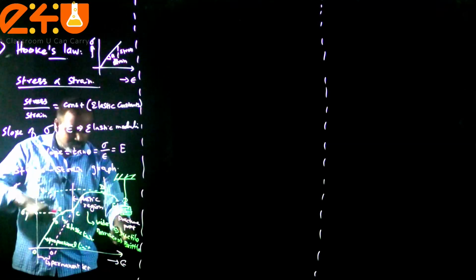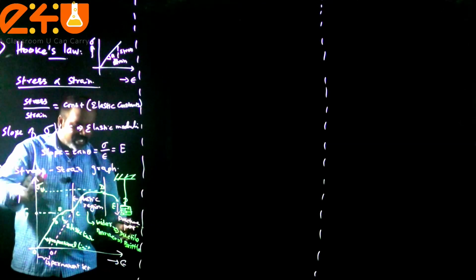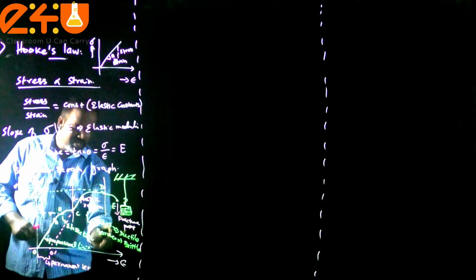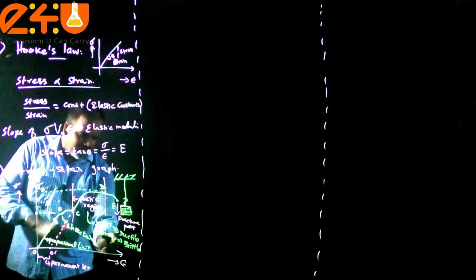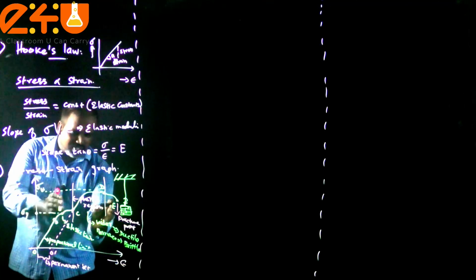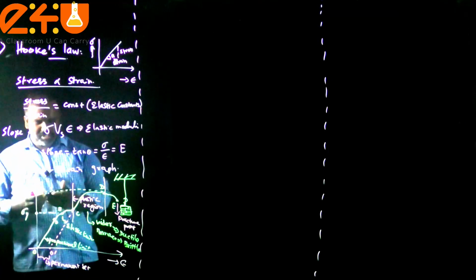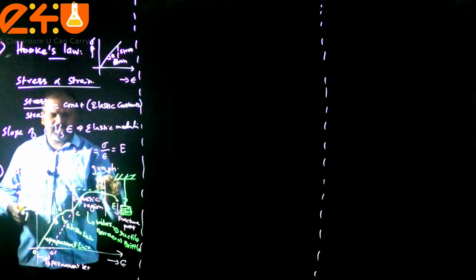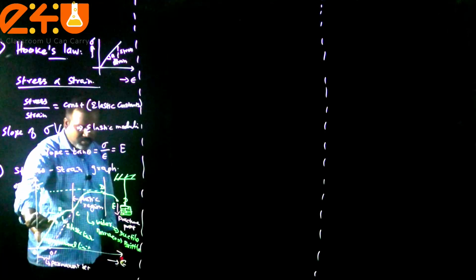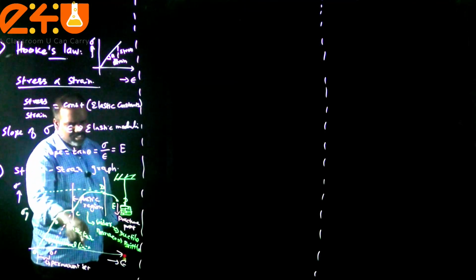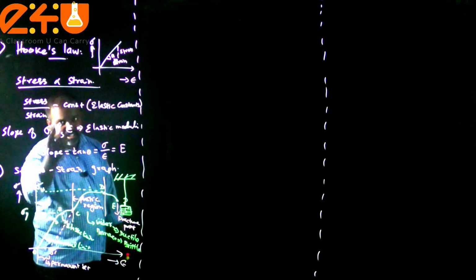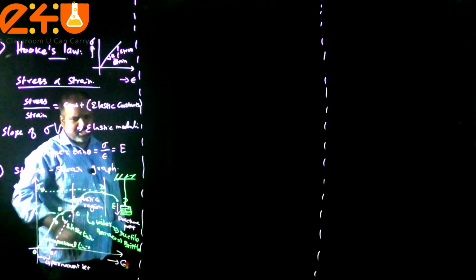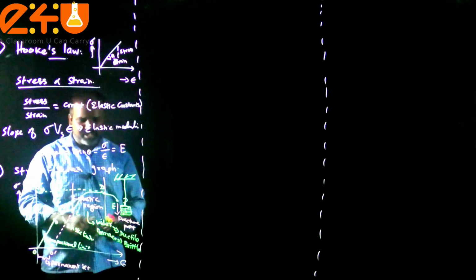Any metal that can be made into a sheet can be said to be ductile, and its plastic region is larger, whereas brittle glass has a narrow plastic region. So this is the important thing we must learn from this stress-strain graph. OA is called the proportional limit and B is called the elastic limit. Beyond that, the directly proportional property deviates from linear to non-linear.